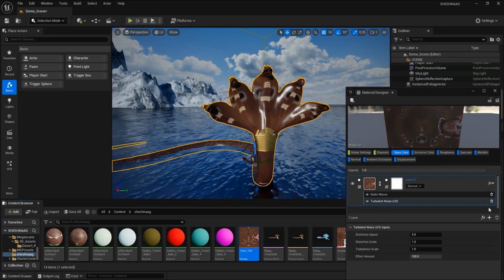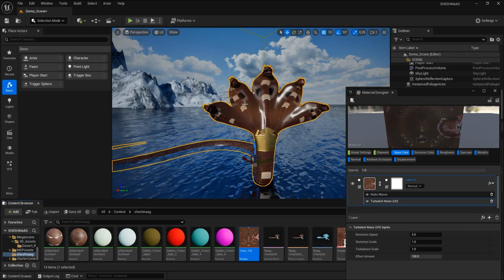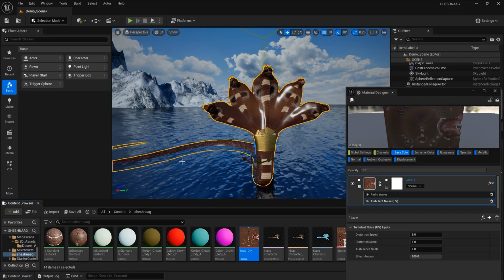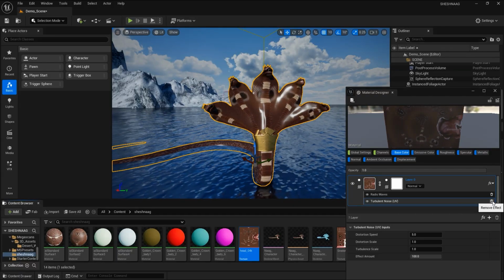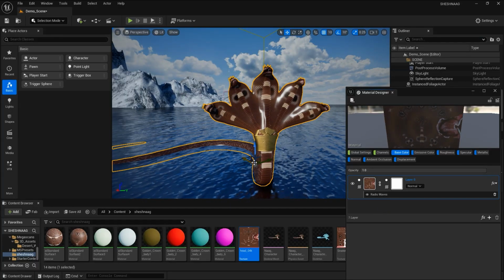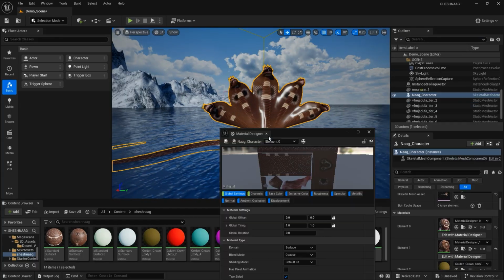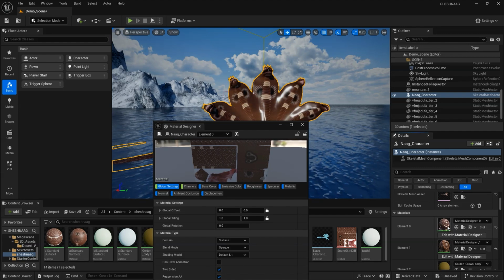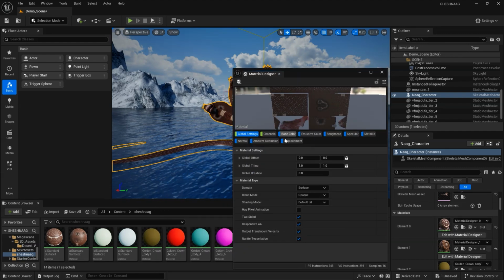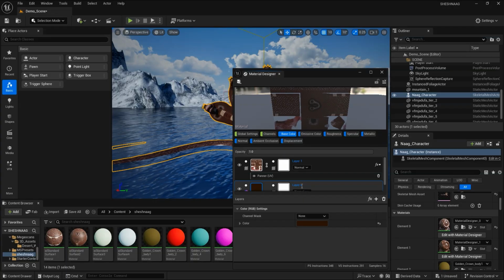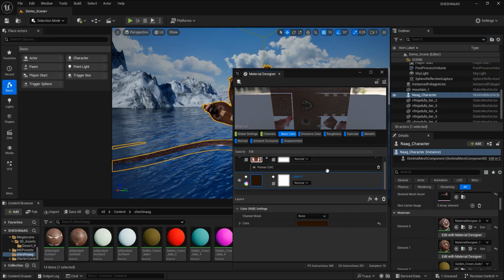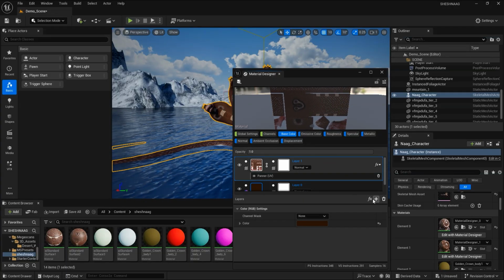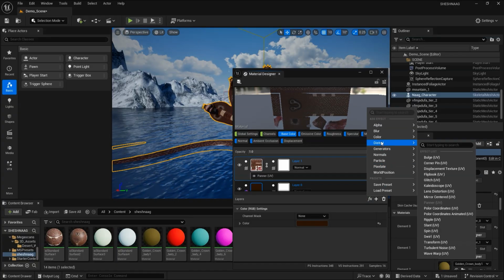Okay, so here we are not going to add it, but in the body part we can add that. So go back, select this, right? And just double click, right? Change the attributes in the base color, right? And over this we would like to add the same effects which are here. Go to the distort, I say turbulent noise.